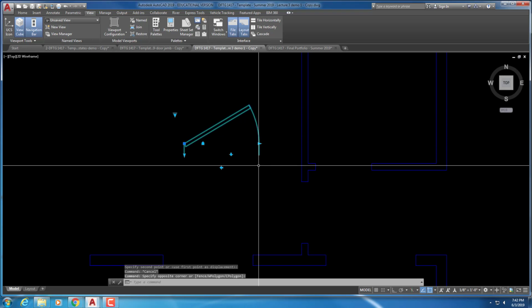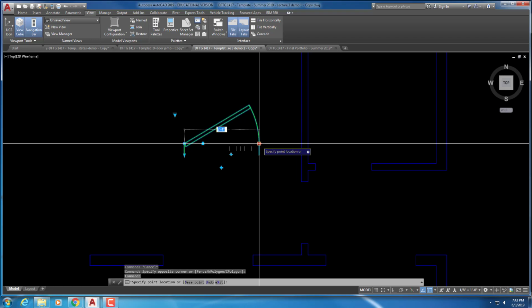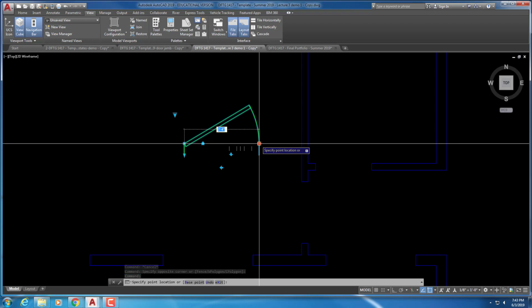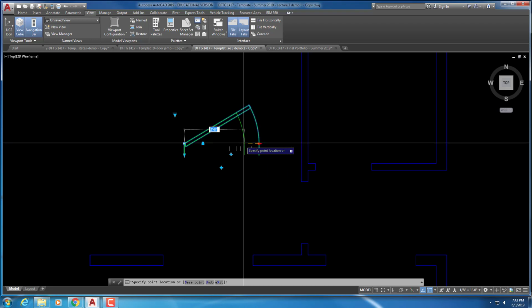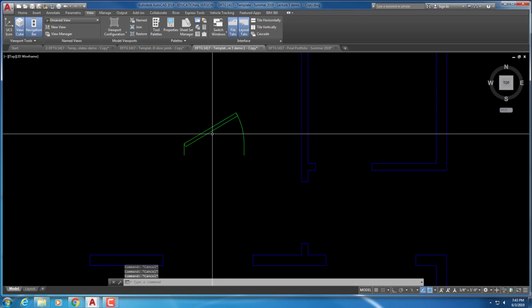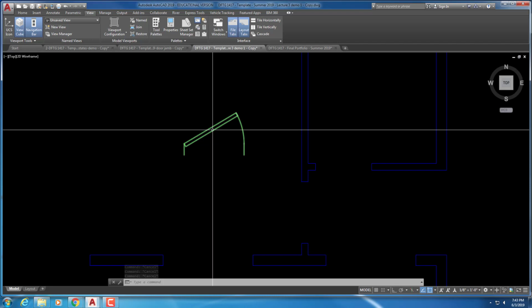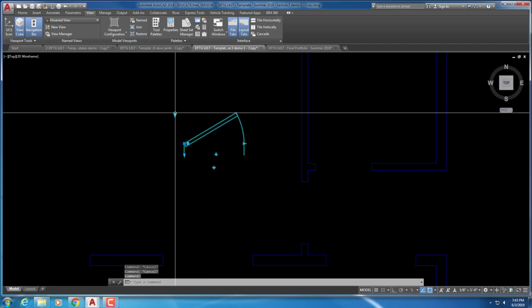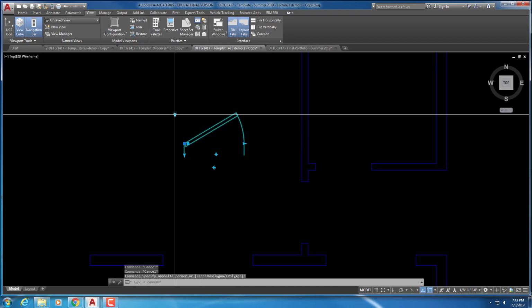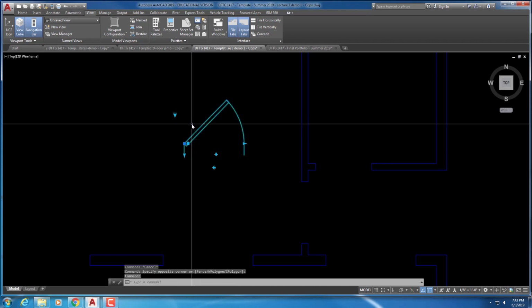One is if you need to make the door bigger or smaller, you can drag it from 2 feet to 3 feet 4 here. This particular door is a 2 feet 8 door. I'm going to want the door to open at 45 degrees, and that's done by this symbol here.